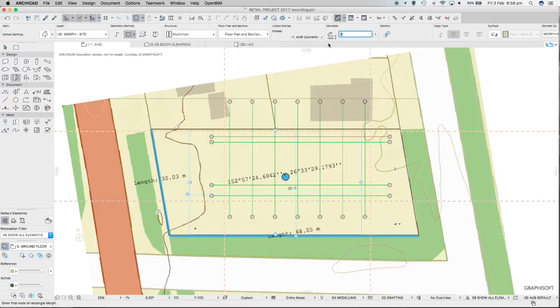I'm going to set its bottom elevation mark to 200 millimeters below the ground floor level. We'll do the finished ground platform 200 millimeters below the floor level. Floor level is 9500, so we'll make this 9300. The other way we could have done this, if we were doing it from ground floor, we would just put in -200 there to achieve the same thing. Okay, so 9300, and then we can start drawing the geometry method shape here.